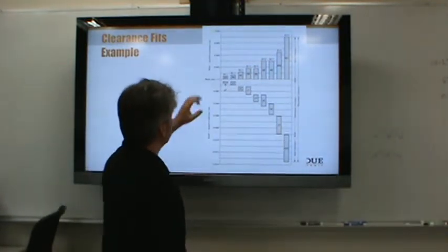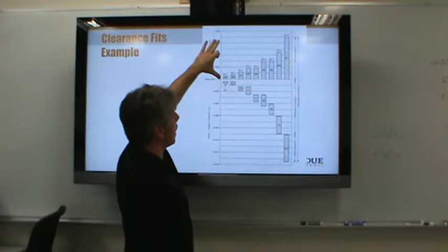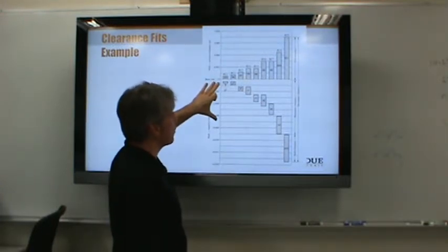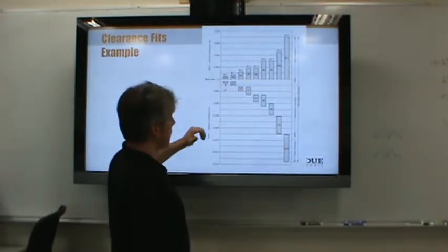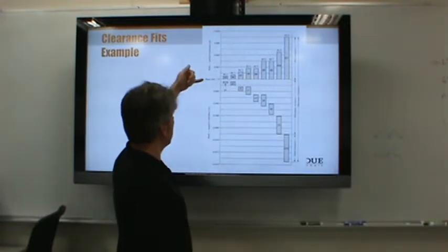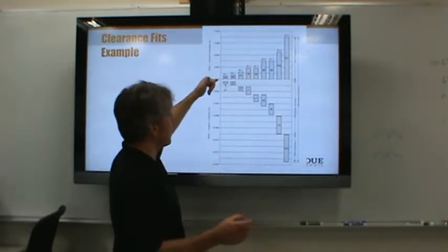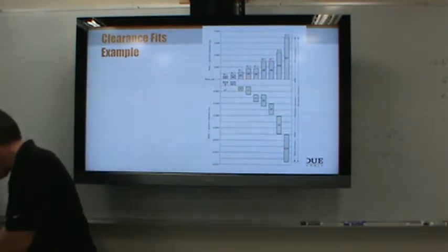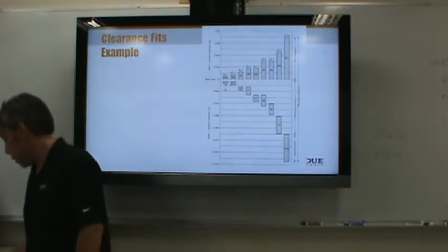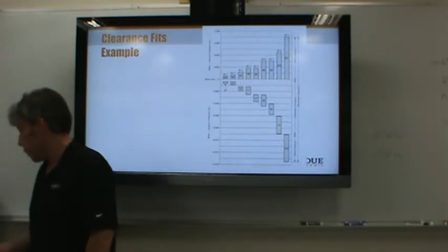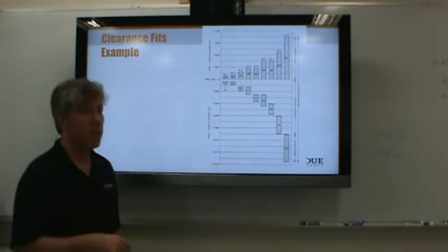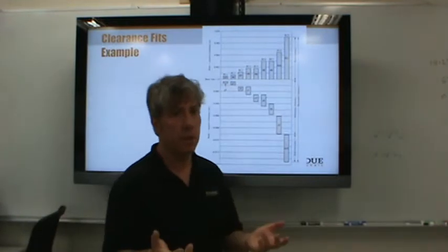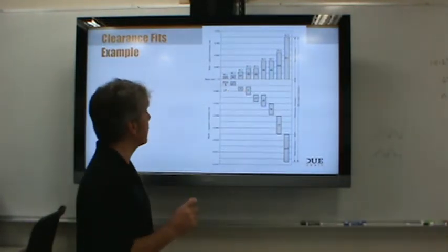All right, so the upper part is the hole tolerance and the lower part deals with the shaft. So the idea is that the basic size is just the nominal size. I think this is for a 2-inch. Yeah, if you look at the note, I cut it off on this, but on the bottom of figure 13.4, it makes a note that this RC fits the basic hole size of 2 inches. So the basic size, the nominal size of the hole and shaft is 2 inches. So that would be the diameter.